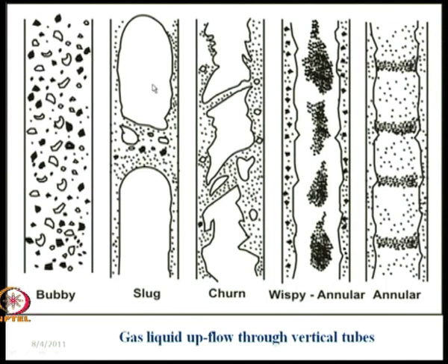Next we come to the churn flow pattern, which is the least understood, least studied flow pattern. There is plenty of scope to study churn flow. It is a totally random, chaotic, erratic mixture of two-phase flow, not very well understood. And after that again we get the annular flow pattern, which is a very well ordered structure with a gas core and a liquid film.